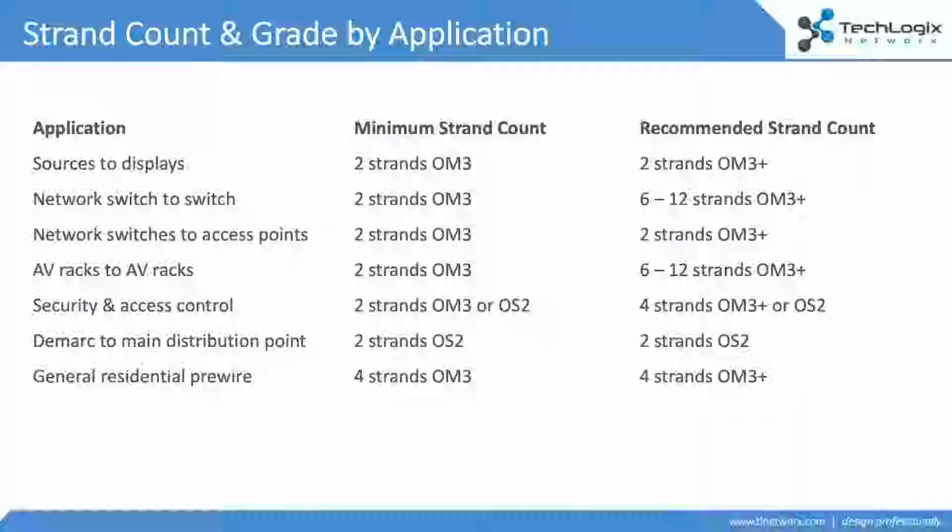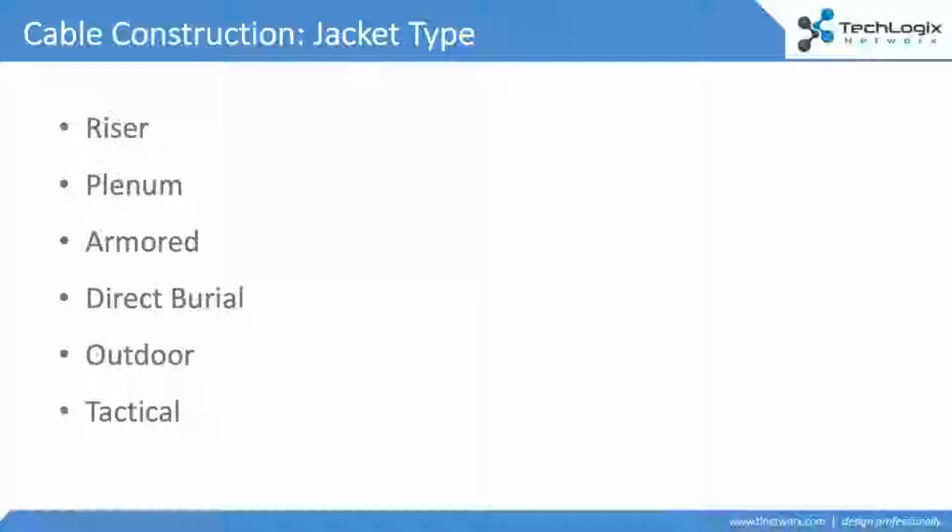And what we see, especially when you're talking about bulk cables, it's usually an OM3 cable, like we were discussing before. OM3 tends to be a standard. We're seeing a lot of OM4 now. If you can pull more strands to future-proof, great. You have that capability. But really, pull duplex at a minimum.